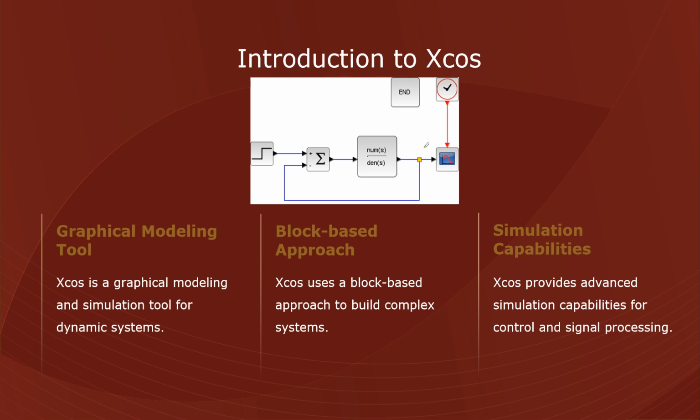It has a block-based approach, like you can see here. This, for example, is a step block. This is a summation block, and this is a transfer function. And there are things like a scope. This is a sink. You can edit the parameters in the sink to edit the final view, the graph that you will get after the simulation is done. And Xcos provides advanced simulation capabilities for control and signal processing.